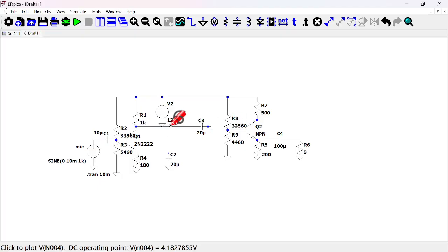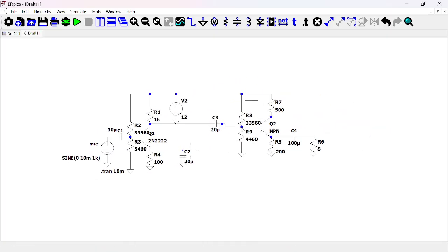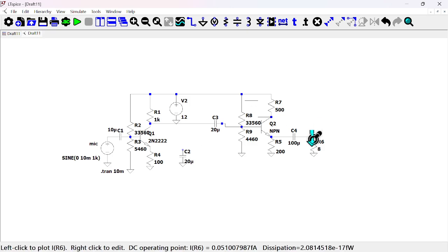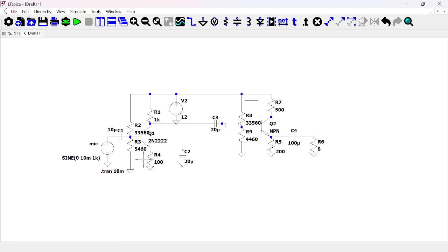So in maintaining the signal here by taking out the bypass capacitor, then at least I still have some reasonable gain with stability in both AC and DC.